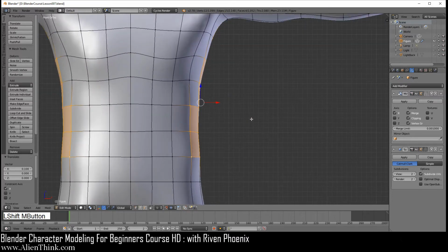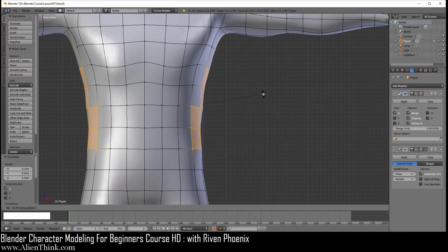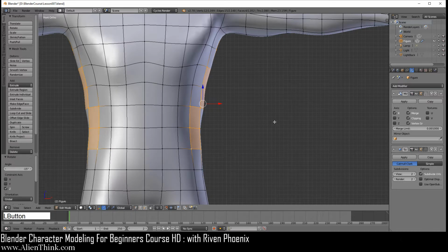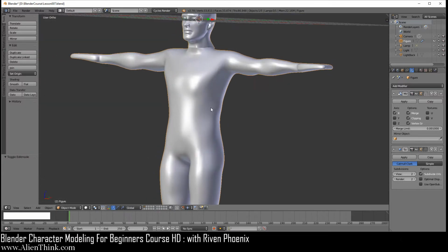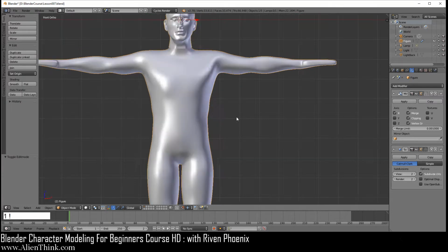Okay. Now over here, we're going to press the R key, then you're going to press the Z key on the Z axis. You're just going to simply go 1 up, move the mouse up, 1, 2, 3. Okay. And again, this is just bringing this area out. These are again just simple landmarks that we need that we're going to manipulate a little later.